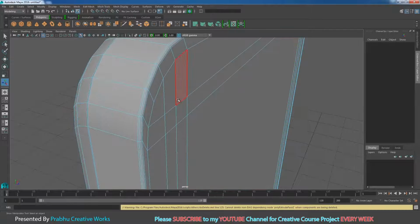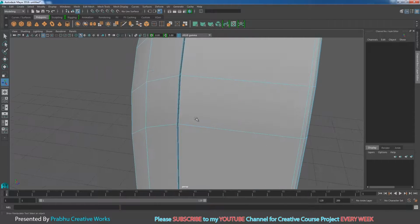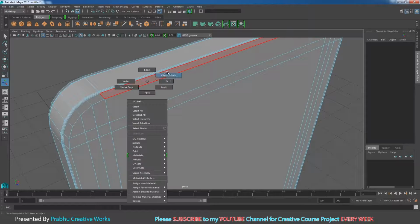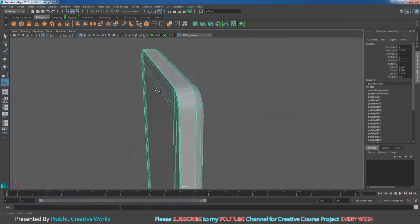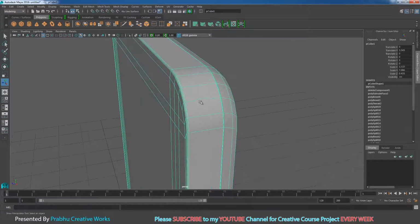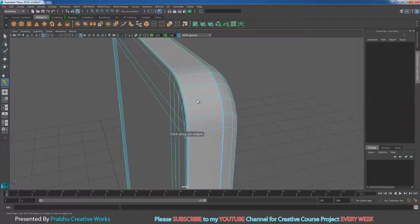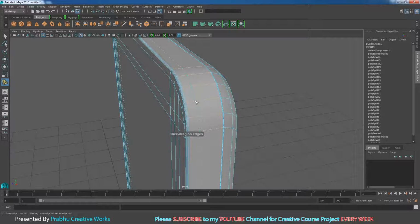So press delete on the keyboard. That means the inner face will be deleted. So right click and choose object mode. Now you want to add an insert edge loop over here. Shift right click and choose insert edge loop. So you want to insert the edge loop over here.